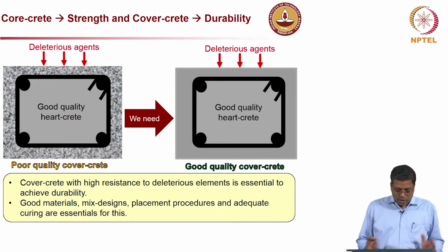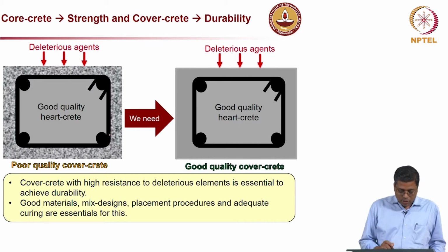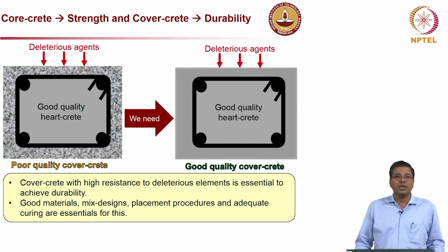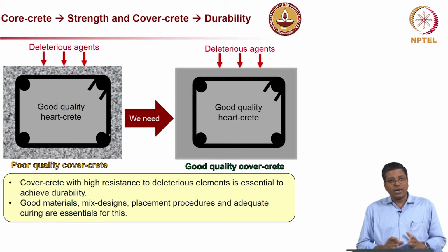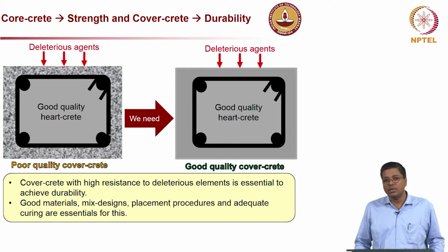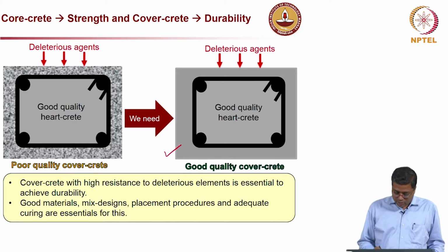So, if you look carefully at the picture on the left side, you will see that the covercrete is of a different texture, basically to indicate that if you do not have a good concreting practice, you might have a very good hardcrete, but the covercrete might still be very porous in nature. So, what we need is something like on the right side, where good quality hardcrete or corecrete, and at the same time good quality covercrete, are essential. So, this is okay, this is not okay.